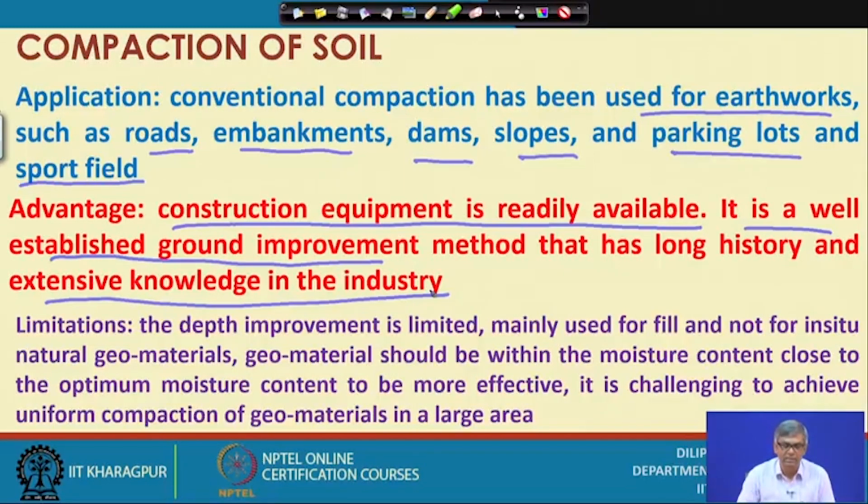That is the advantage, and there are some limitations also. With compaction equipment like rollers, you get a very thin compacted layer; the depth of effect does not go much. Because of that, we work with a particular lift thickness, and it is mainly used for fill and not for in situ natural geomaterials.